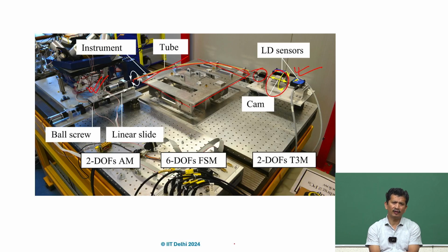But if we design it so that all the forces are in tension, we can imagine taking a steel wire of 1 millimeter diameter and a length of, suppose, 20-30 millimeter; we can do the calculation and check the load bearing capacity. Even the stiffness can be very high because it is EA by L. It is all axial stiffness we are talking about.